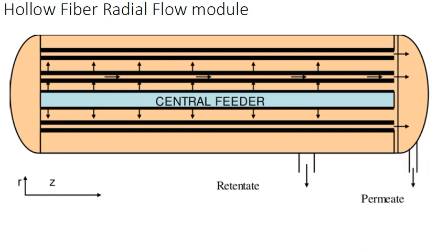Okay, now this is the special geometry used for reverse osmosis, especially for seawater desalination, where you need a very large membrane area because the fluxes are very low. Why are the fluxes very low in seawater desalination? Because the concentration of salt is very high in seawater, so you get very low fluxes, and the pressure requirement is very high.